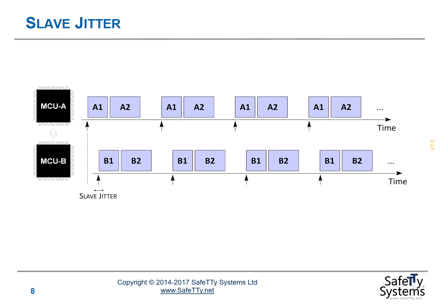As we touched on previously when we first looked at shared clock schedulers, we'd usually expect a shared clock scheduler to be run on a network in which there was no other traffic. So we have a complete TDMA protocol. The consequence of that would be we would expect the network to be clear when we send a tick message. So we're not expecting jitter to arise because we cannot send the tick messages because there's some other traffic on the bus. That would generally be an error situation in this type of design.